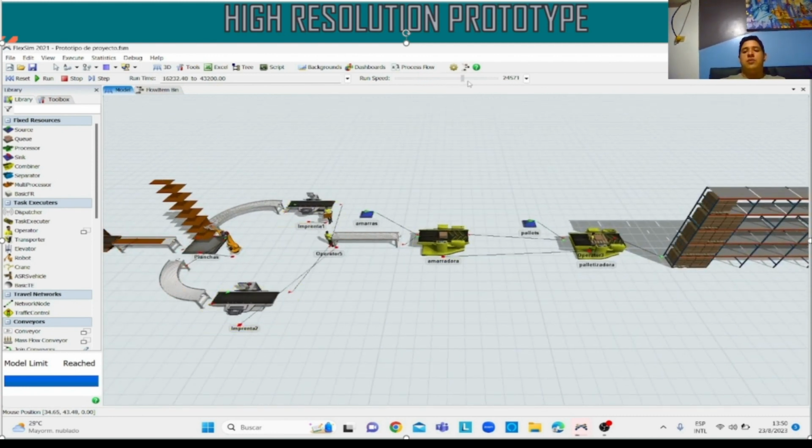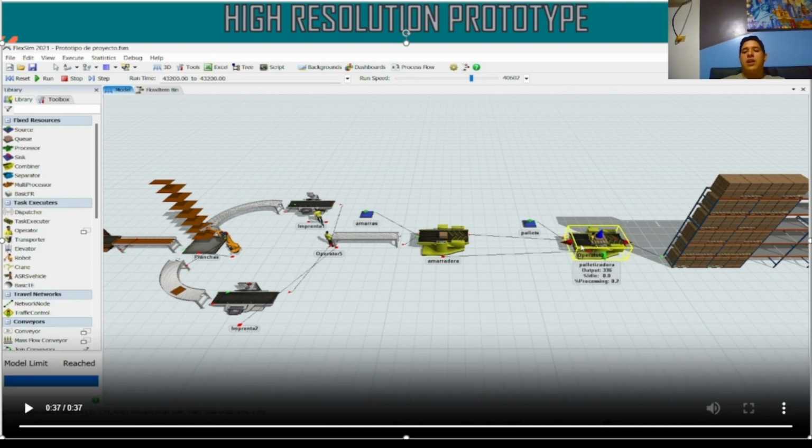Our project focuses on the optimization of the transfer time of cardboard sheets from the corrugator to the presses. To accurately simulate these processes, we consider that the corrugator on the plant produces 30 meters of corrugated cardboard per minute. Given that we are working with 1 meter long sheets, the processing time will be 2 seconds for each of these sheets. Furthermore, we know that the setup time for these machines follows a normal distribution with a mean time of 10 minutes and a standard deviation of 2 minutes.